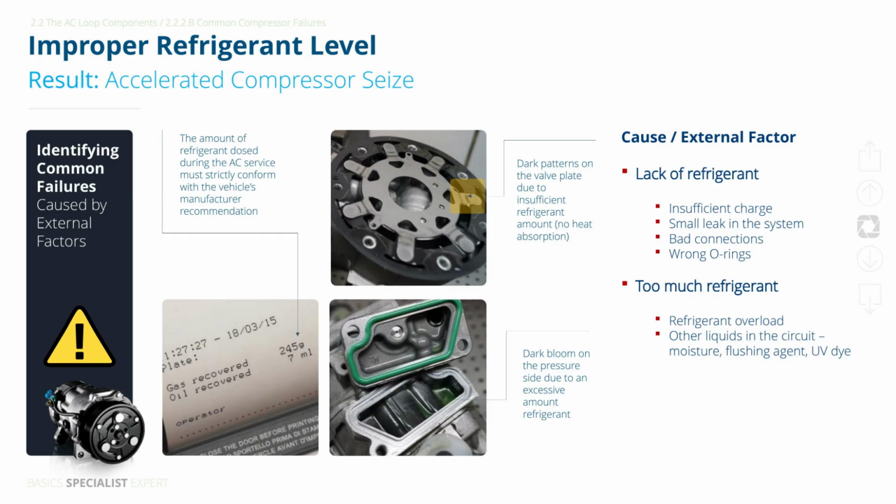Too much lubricant, or the wrong kind, like moisture, will eventually take out a compressor by overheating it. That's why technicians need to be precise and careful with every AC service procedure they perform. Additives are fine when used as directed. But overusing them, or using the wrong type, can quickly lead to compressor problems.